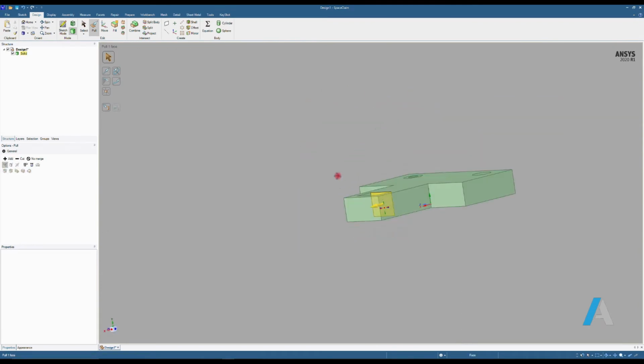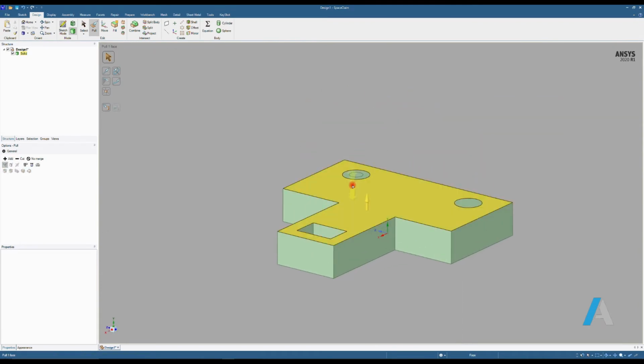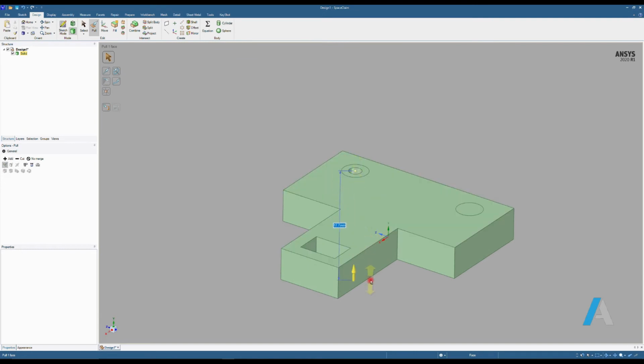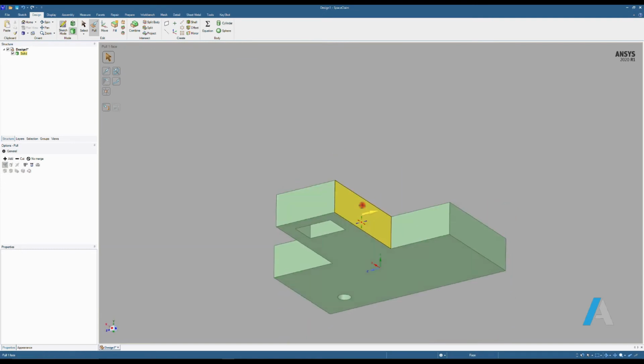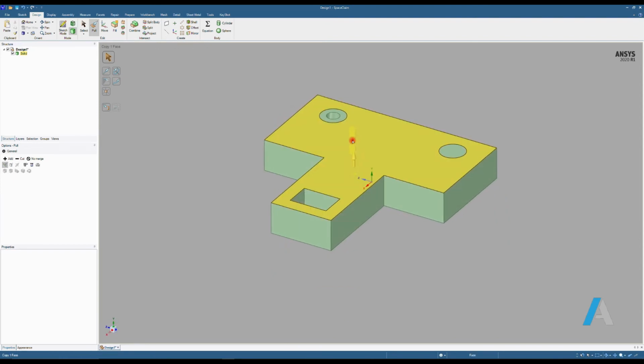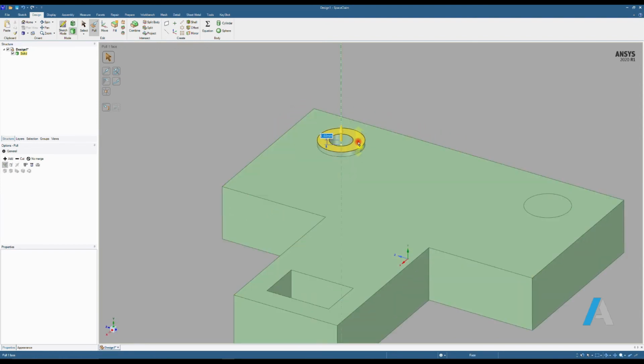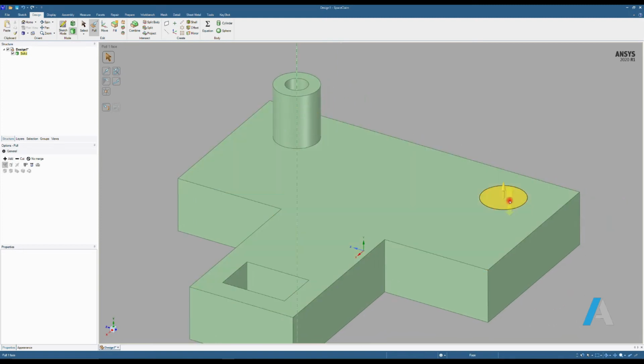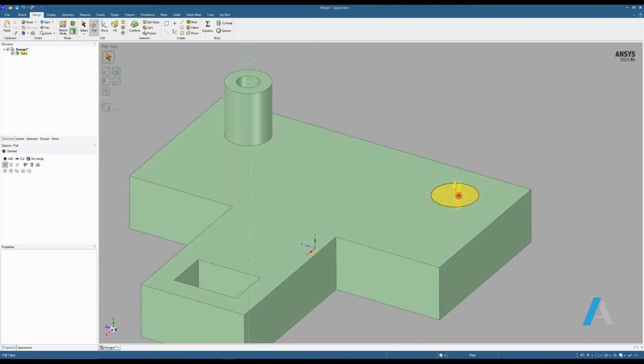I'm going back to 3D. Again, pull. We need a hole here. Easily cut that circle out, and now I'm going to create this cylindrical face. I'm going to add 5 millimeter dimension here. And now for this guy here, what I'm going to do, I'm just going to pull. And now I can create a circle on top and then cut it out from here.